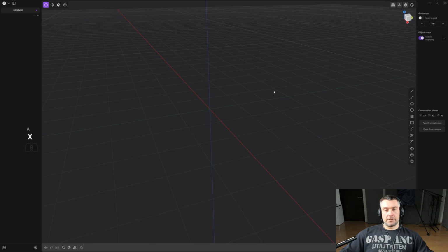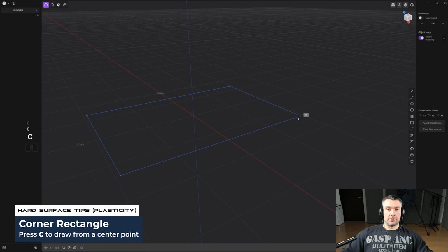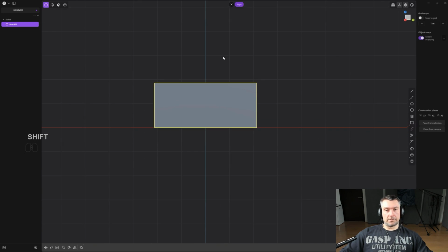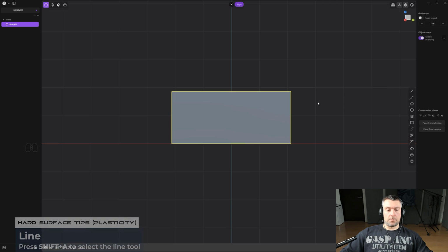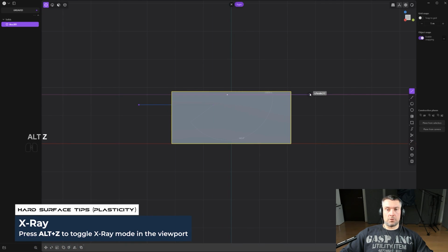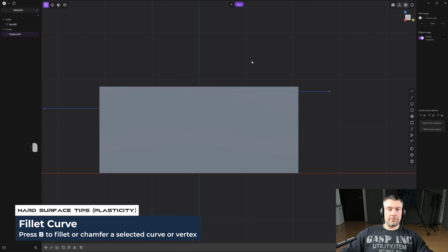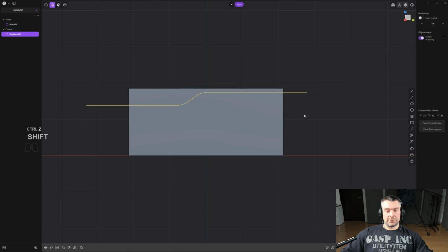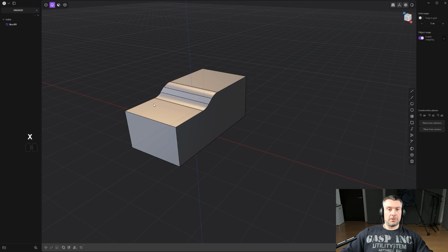All right, so now let's talk about another thing, that's cutting with curves, because it's also very, very useful. Let's say you have a cube here, so we're gonna draw a cube, right? And by the way, when you're drawing a cube from a center, you can press C to toggle and draw from the middle like that, right? So let's say I wanted to slice it very quickly with a specific shape, just like with Ngon in Blender using box cutter. So I can grab this edge here, press Shift A, and I can start drawing a shape, right, like this. And if you can't see a shape, press Alt Z, and draw a shape here, and approve it. Press 1, select this by drawing from the left corner, drawing like a rectangle. Press B for bevel and move it up to create a bevel, and then with this curve selected, right, press C, then select the body you want to cut and right click, and then X to delete it and delete your curve, and you got a really quick boolean.